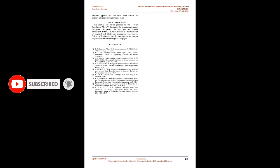The SSD1306 embeds contrast control, display RAM, and oscillator, which reduces the number of external components and power consumption. It has 256-step brightness control. Data/commands are sent from a general MCU through the hardware selectable 6800/8080 series compatible parallel interface, I2C interface or serial peripheral interface. It is suitable for many compact portable applications, such as mobile phone sub-display, MP3 player and calculator, etc. The IC supports both 3.3V and 5V logic devices.